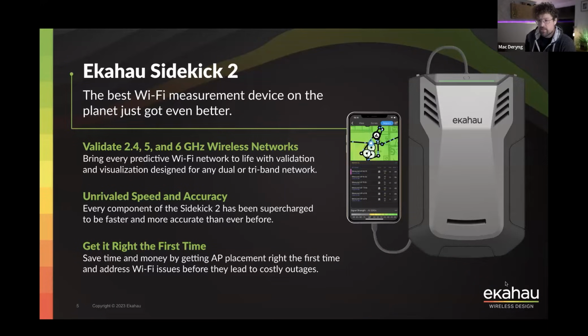And because of the dongles' inaccuracy and difference in readings, every time you do a survey, sometimes when the RSSI measured by a quality device like a Sidekick says it's minus 60, on the dongle, most likely you will see around minus 60, but sometimes you will see minus 85, sometimes you will see minus 45, and the difference is unacceptable to have in the Wi-Fi world. And also, we want to have everything in a single device. We don't want to have tons of different dongle Wi-Fi cards. We would typically have 3 of those connected to a USB hub, sitting on the Velcro on the back of our massive laptop screen in the past.